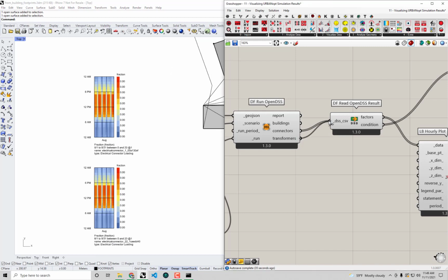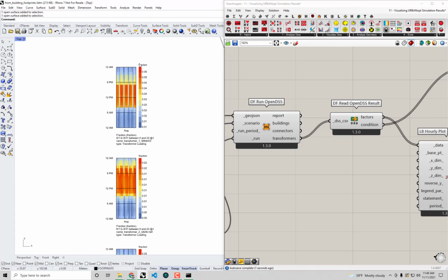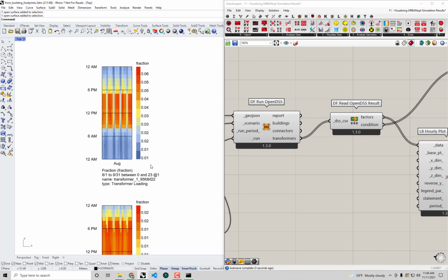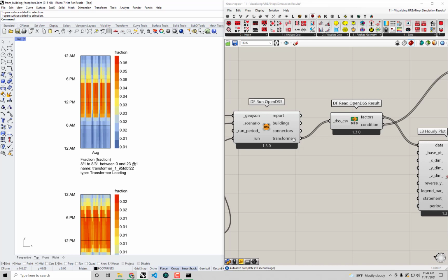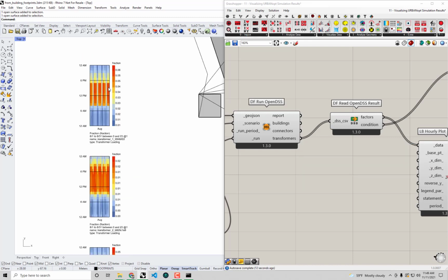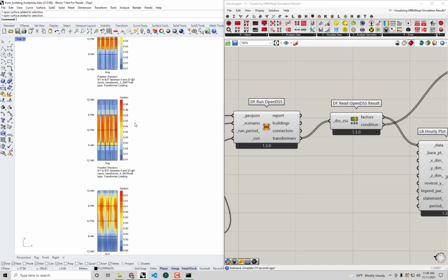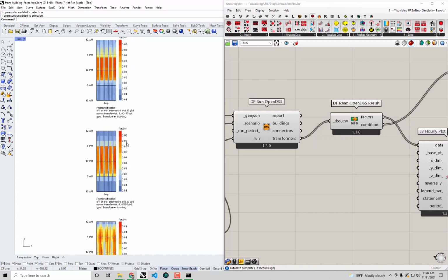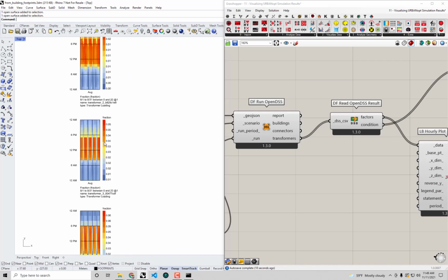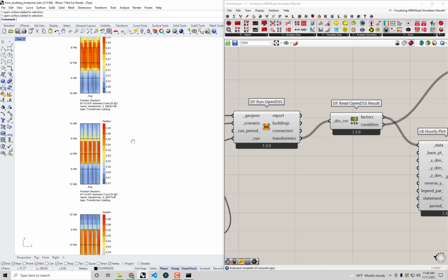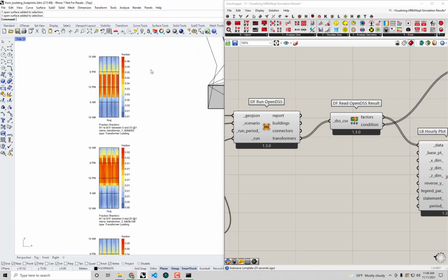And then lastly, we can take a look at these 5 transformers, right? We can see the factors here, and okay, we're starting to get some factors that are a little bit higher here, right? I guess this should be the loading on the transformers. So these are a little far from unity. Maybe, I don't think they're that far. I know if you search through the guidelines on OpenDSS, they'll give you guidance on what factors are at a point that may be concerning.